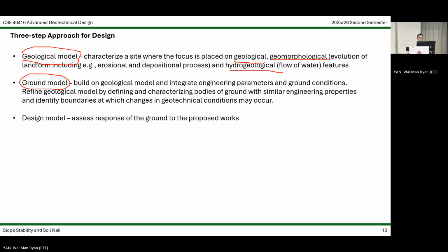With the geological model alone, we cannot do the design, because in many cases, those geological models are too complicated. Maybe from your log, you see 1 meter of grade 5, and then another half meter of grade 4, and then come back to 2 meters of grade 5, and then 1 meter of grade 4, like sandwiches.